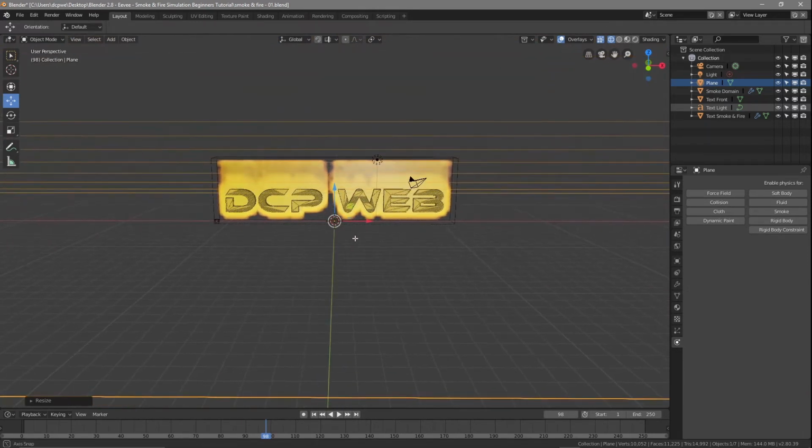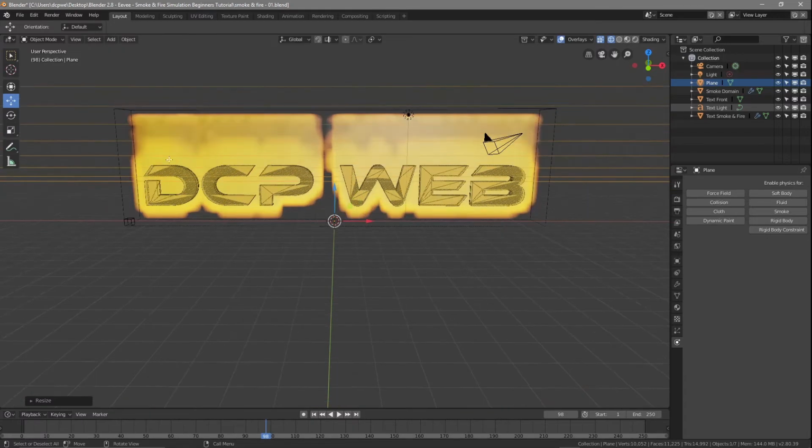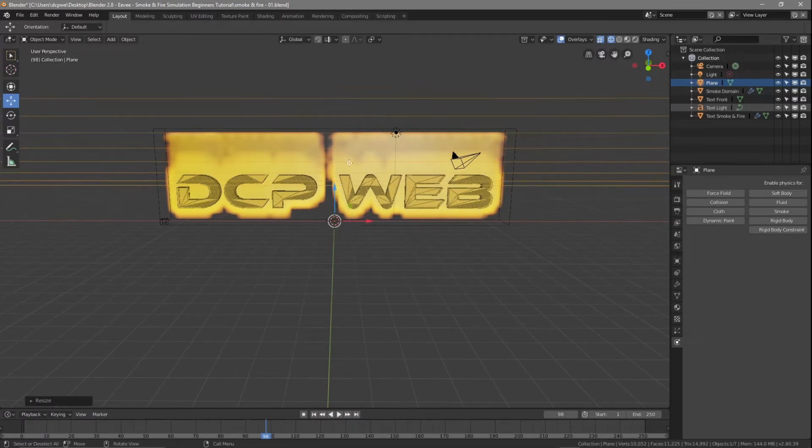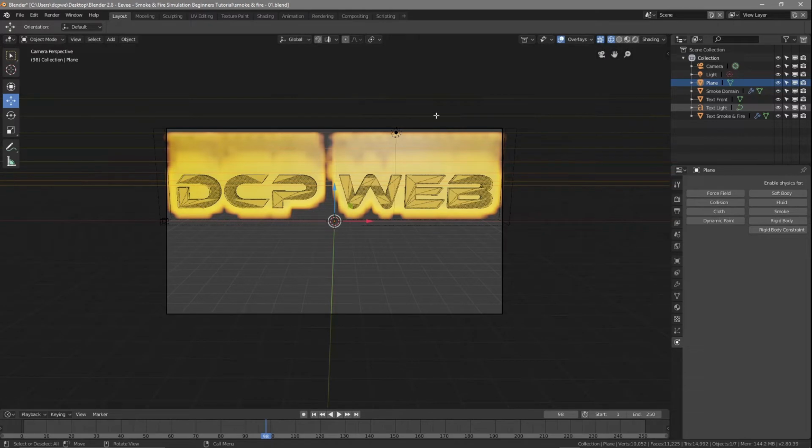and what we want to do is sort out the camera. You can see the camera is right here, but we want the camera to see what we can see in terms of this text here. So to do that, all we're going to do is press the Control, the Alt key, and hit number 0. So Control, Alt, and 0 will move the camera. So the camera's moved from that original position to what we can see.